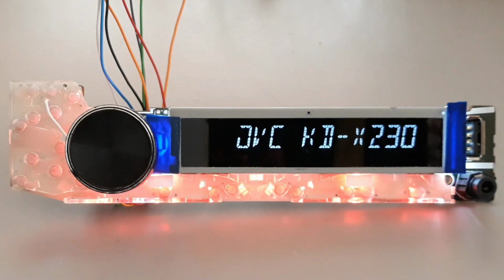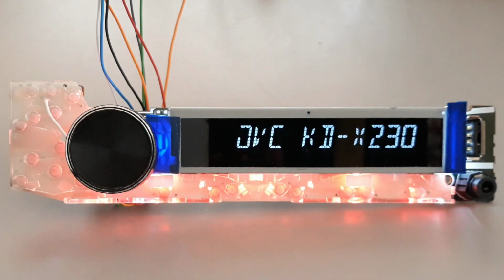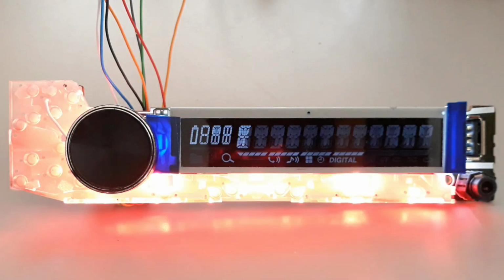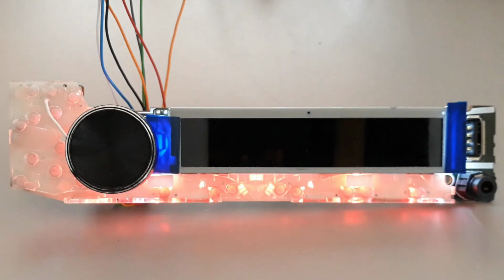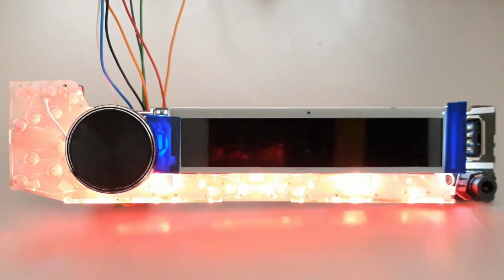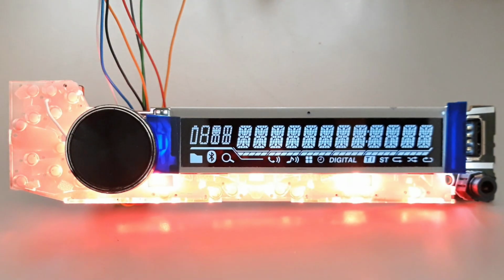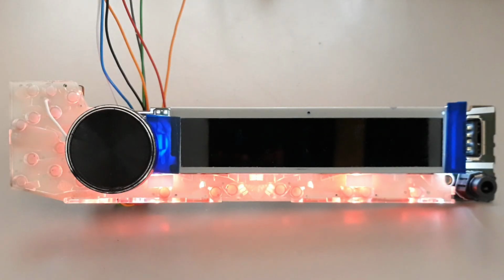However, it would also be possible to use a 2.2 kΩ resistor, saving one Arduino pin. And, as always, it is essential not to forget the common ground reference between the panel and the microcontroller. After implementing everything described here, the panel is fully operational and ready to be reused in new projects.